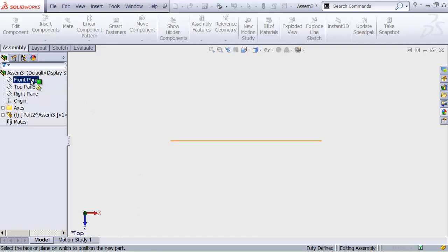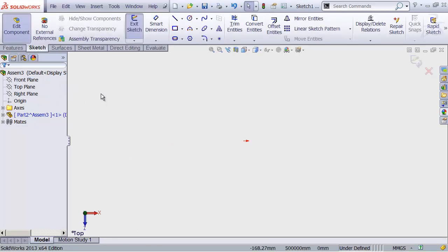Okay, so let's click the front plane because that's where we want to position our part. And we're going to do that as a matter of habit, by the way. When you create a new part, just click the front plane. And then I'll click our new part twice, and I'm going to rename that plank and hit enter. Now if I deselect that by clicking out here in space, you'll see that our plank is bright blue, or at least the title of it is, and that means that it is the active part in our assembly. Further, our sketch toolbar at the top of the screen has appeared, and over the top right of the viewport, there are a couple of new buttons here. And as it happens, this little pencil icon means that we're currently editing this thing called a sketch. We're going to talk about that in a minute.